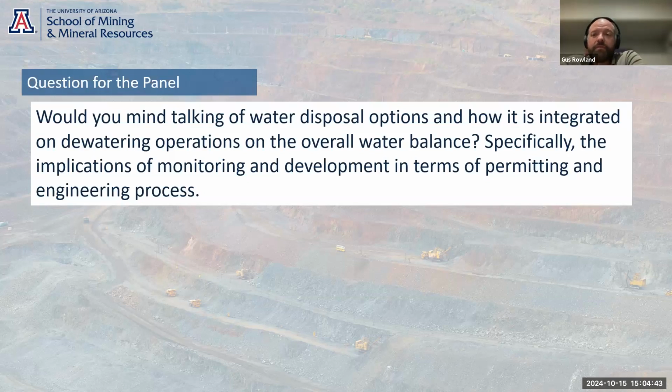And so making sure that from the very beginning, you're encouraging flow monitoring, flow measurement, quality measurement at every stage of the process, and making that a completely integral part of managing the system is really important. So that's where that monitoring comes in. You can't understand the system if you don't know exactly where the water's going and what it looks like when it gets there and where it comes from.